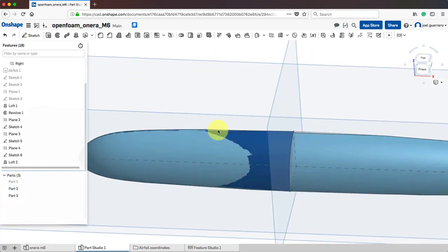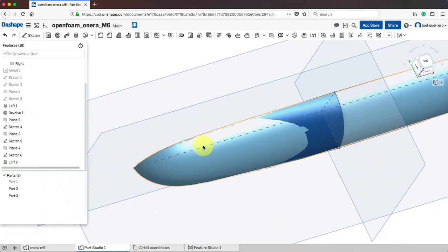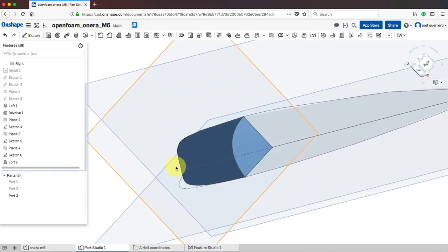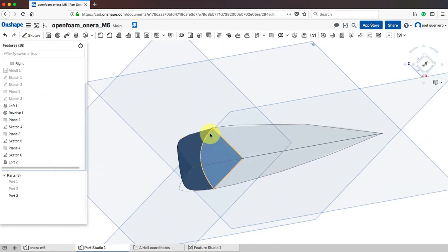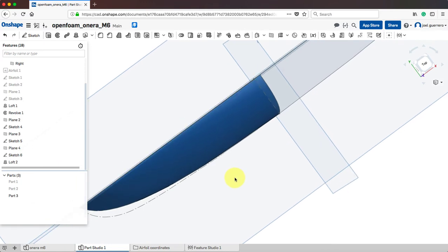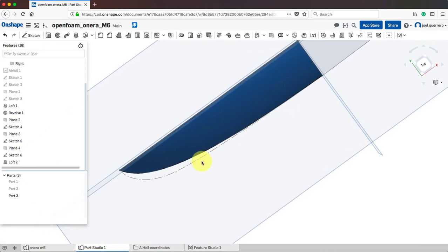See that this one is very rounded here, okay? Instead, look at this one here that is losing control. At the beginning, it's following this curvature, but then it doesn't follow that shape. So what I can do here is add another cross section to have more control.